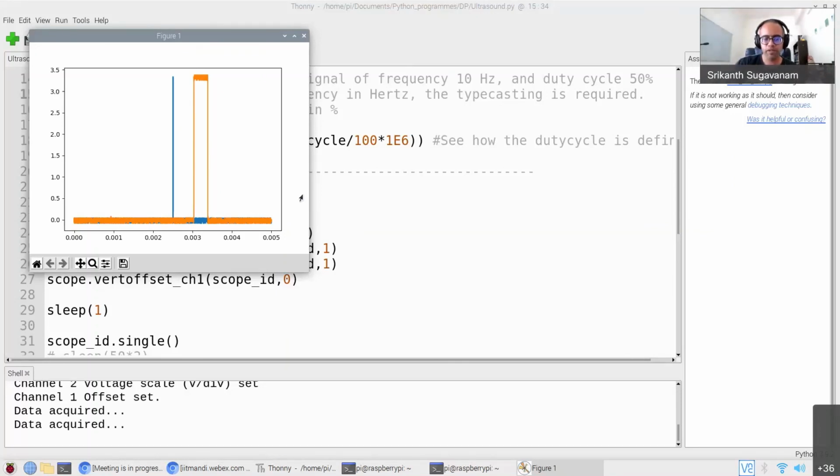The other problem with the Raspberry Pi is you cannot do real-time applications with it. When you're using an Arduino, you remember when I showed you the accelerometer function. I was actually acquiring data in real time, and every time the data was getting sampled, there is a timestamp associated with it, and it is well quantified. I cannot do the same with the Raspberry Pi.